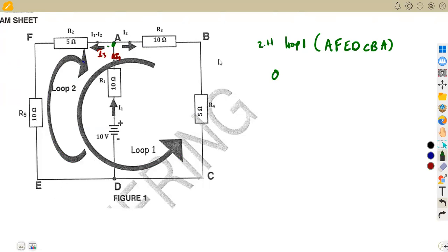That is the voltage that we have as our external voltage source at the end. But now we need to multiply the current and resistance following the direction that we're given, so that we have the voltage drops. So we are going to calculate the voltage drops of each part. The first part starts at point A, following this direction.